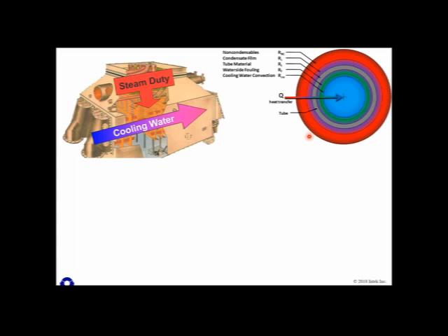And I'll show measurements of this in real condensers to show you that steam can actually be shut off on given tubes. It's pretty amazing. Moving along, the steam travels through this partial pressure of air, or non-condensables, and then the next layer is a condensate layer, and so there's a thermal impedance of that condensate layer. This is dripping condensate. Again, the tubes on the periphery of the bundle have that water being stripped off, and so that R value is quite low. But where tubes have a high condensate load, then that can become a significant impedance to heat transfer.